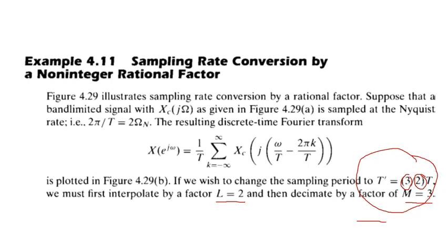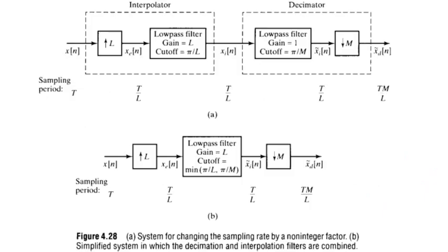So let's have a look at an example in which we are performing all the functions, that is upsampling and downsampling. These are the separate blocks of interpolation. As I've told you, in order to avoid aliasing, we use a decimation filter, and then we perform the downsampling.